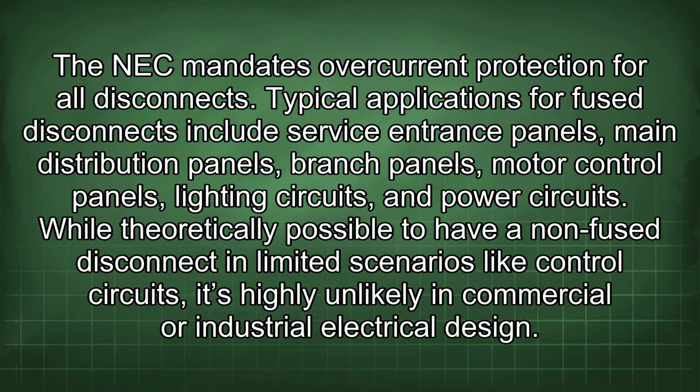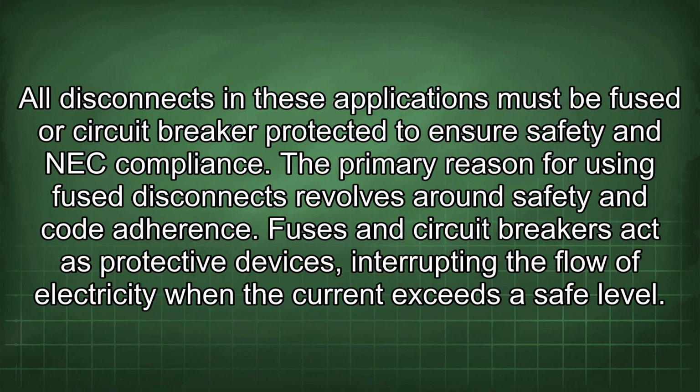Typical applications for fused disconnects include service entrance panels, main distribution panels, branch panels, motor control panels, lighting circuits, and power circuits. While theoretically possible to have a non-fused disconnect in limited scenarios like control circuits, it's highly unlikely in commercial or industrial electrical design. All disconnects in these applications must be fused or circuit breaker protected to ensure safety and NEC compliance.